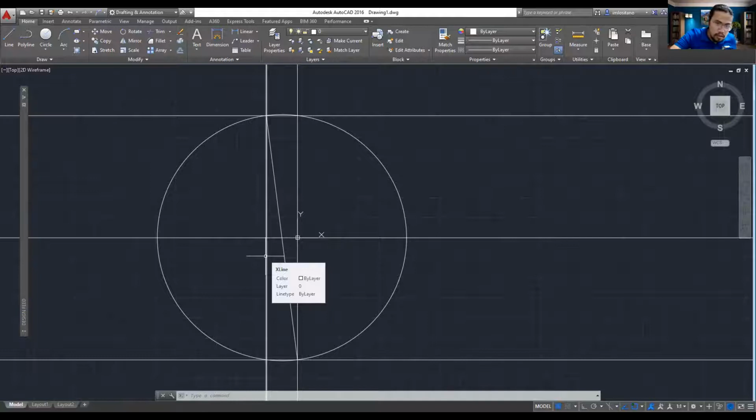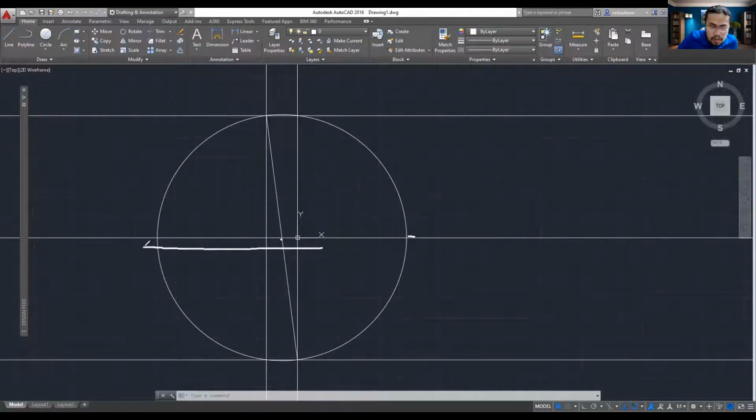Primarily, our first principal stress that we will be able to identify is this one. Our principal stresses are along the x-axis, so we just have to measure this first line, and the other one is going to be along this direction. And we have our maximum in-plane shear stress along this line.